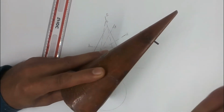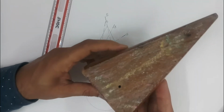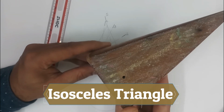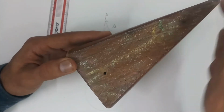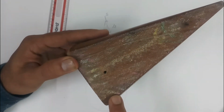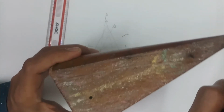Whenever I cut this cone like this, we can see the true shape of section is going to be a triangle, and more specifically in most cases it is going to be an isosceles triangle, because in most cases the diameter of the base circle and the height of the axis of the cone are such that the shape of section is an isosceles triangle, with this as the base of the triangle, and these two are the two equal sides of the triangle.